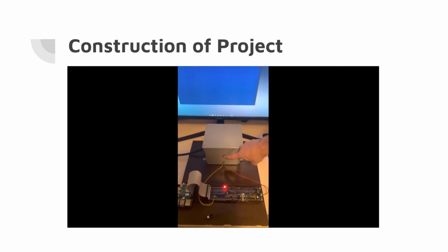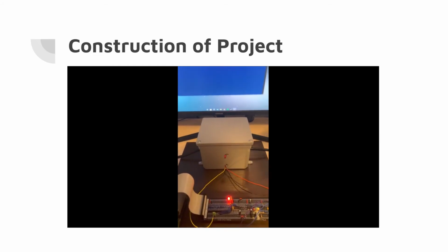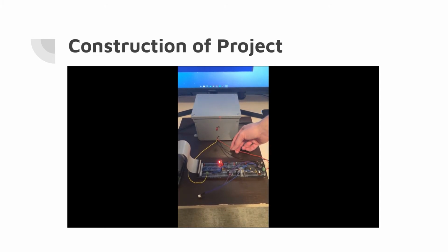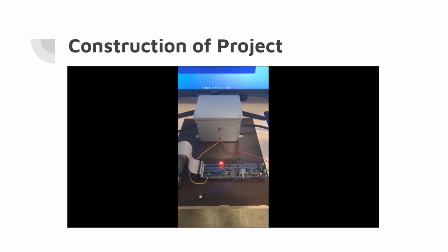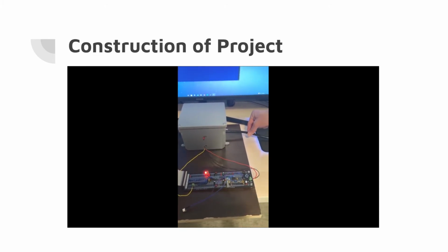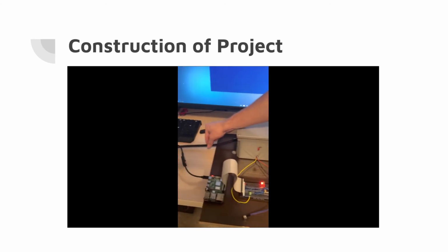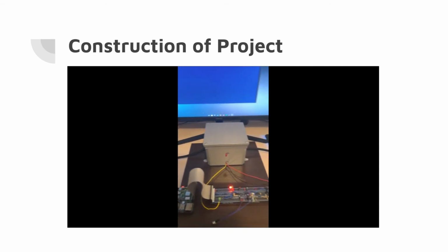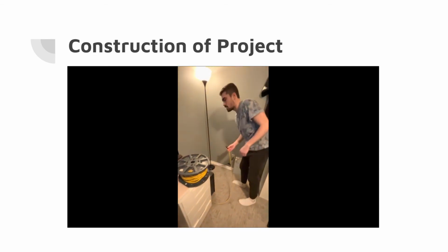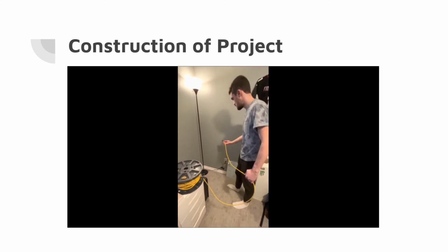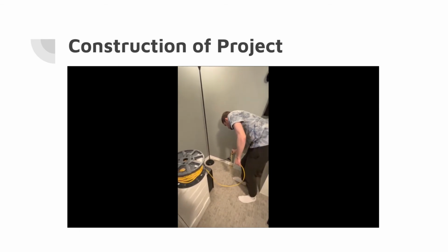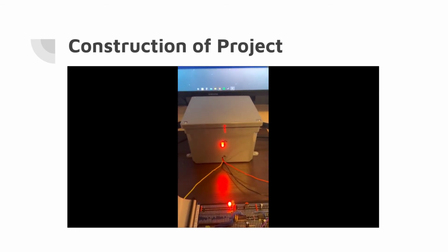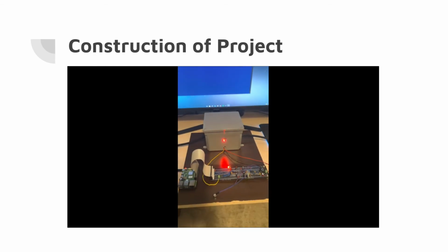On the front end, we have a circuit breaker status light, which will be on when the circuit is live. We have the connections to our main switching component, which is the relay module, and that is connected to our DC circuit. This is the AC in cable, and this is the AC output, which we have connected a lamp as our output for this demonstration. If you come with me to the right, we have our AC input connected to an extension cable. When I plug this into the wall, you will see that the circuit breaker status light is now on, like I said before, indicating that the circuit is live.